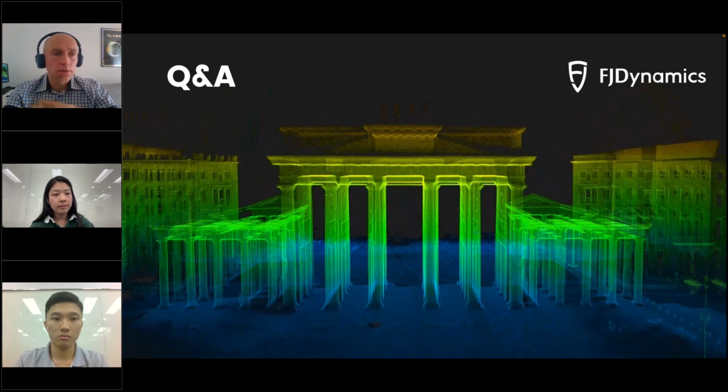I also advise do not rush in starting your scan. Wait 30 seconds. I usually wait 30 seconds to let the scanner collect a lot of points from the starting position. It helps a lot, and of course move smoothly. And transitioning between rooms is the key, the crucial element of your scanning, because you probably get misalignment when transitioning rooms improperly.